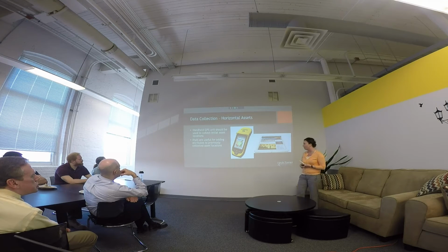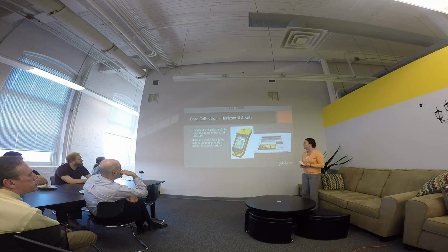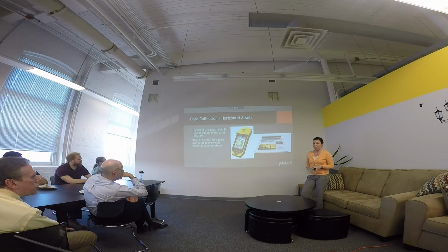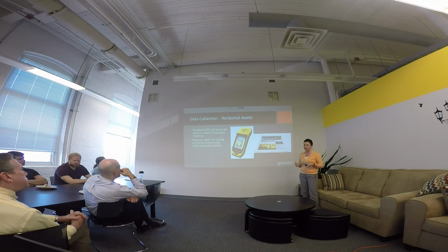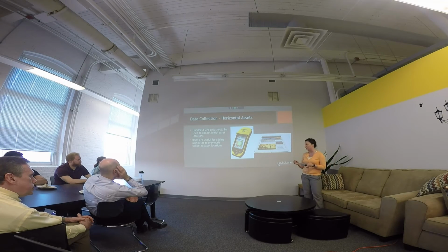The Trimble allows sub-meter accuracy, which is 3.28 feet, as opposed to something like an iPad. iPads are very useful in data collection, but not if you don't know where your locations are and you really want to focus in. The advantage to iPads is that they're easy for people in the field to use, like DPW workers. So if the points are already collected using the Trimble, then it can be modified easily.